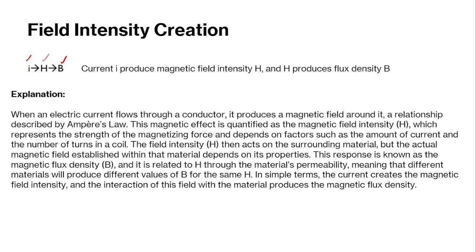I have a question, right? Ampere's circuital law is only applicable for a closed loop, not if it's an air gap or if it's different materials. Correct. Yeah, well done. We can go through that, but yes, that's a good observation. As for Ampere's circuital law, it has to be a closed loop. If it's an open loop, tough. But there are ways to simplify it in order to use it. Yeah. So that is good.